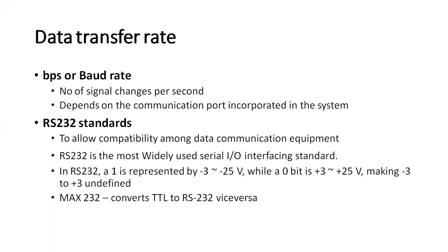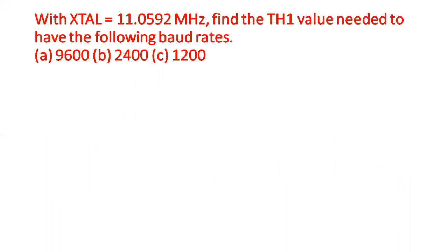So the MAX232 will convert vice versa, right? The microcontroller signal is TTL logic, and RS-232 logic has a different voltage level. So it will convert the voltage levels vice versa. That is the purpose of using the MAX232 IC.